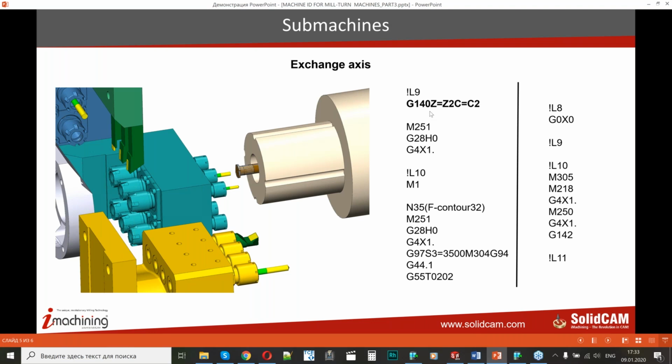What else does it mean for the programmer, for the operator? It means that while I have operations on a back tool post, I can't have my Z and C operations on the first channel: Z1 moving the stock and C1 rotating the stock. So I don't have operations on the first channel when I have operations on the back tool post. This is a special feature of this machine.